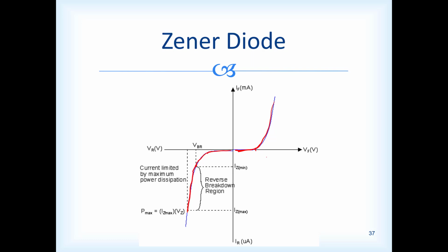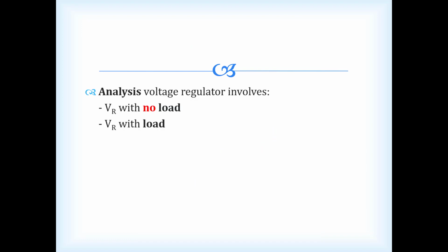When the breakdown occurs, there will be surge currents flowing. But the one special thing about the Zener diode is that it's reversible, meaning after a breakdown, when the voltage is reduced, it will come back to being a usual diode. But if it's just a normal diode, once it breaks down, then it's broken down. It no longer works as it normally did. So this is the special thing about the Zener diode.